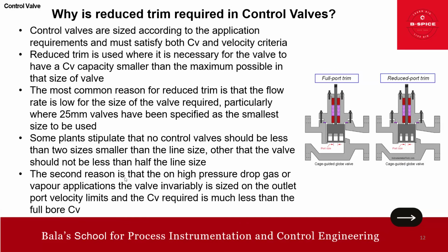So the second reason is that on high pressure drop gas or vapor applications, the valve is invariably sized on the outlet port velocity limit, and the CV required is much less than the full bore CV. I don't know whether you got it.